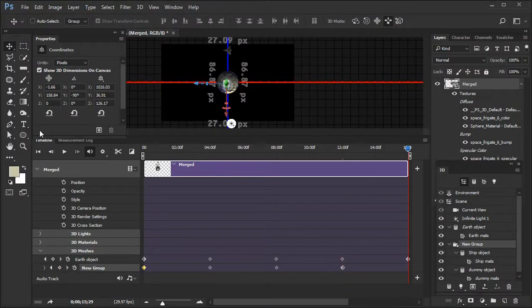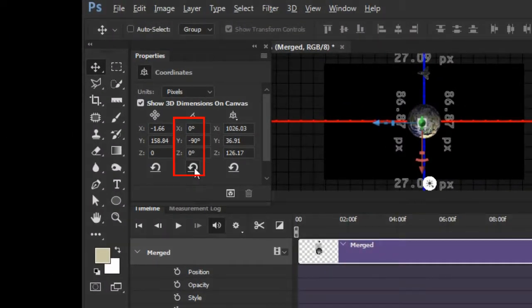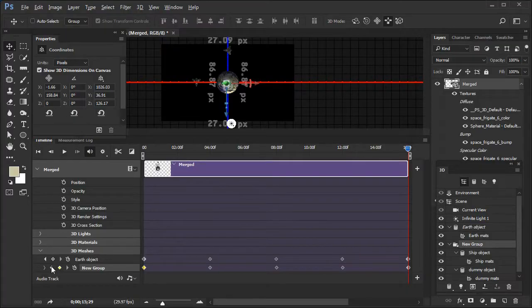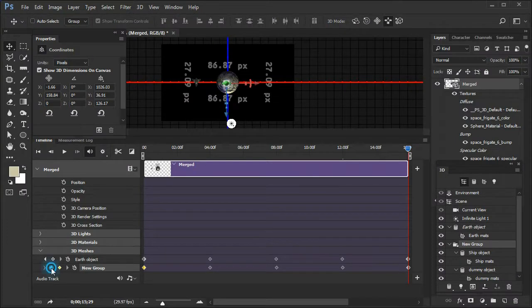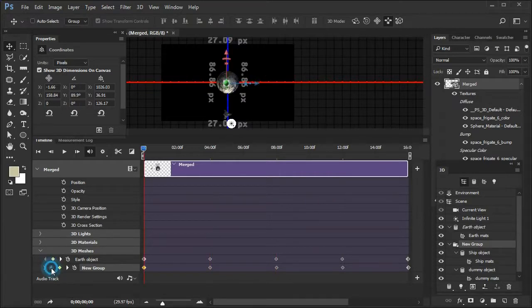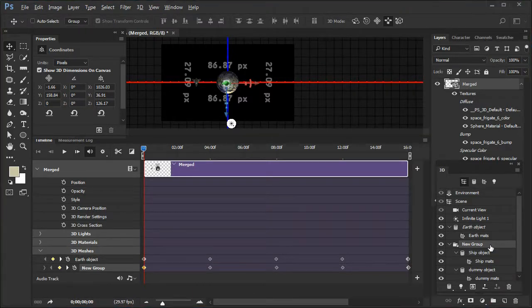Finally, press the End key to go to the end position. In the second column, press the Reset Coordinates icon, which will change all the values to 0. Now move back to the 12-second keyframe. Then move forward to the end keyframe. If it is not still 000, change it so it is. Now check all the keyframes starting at the ending and working backward using the left triangle icon, just to make sure everything is as it should be.